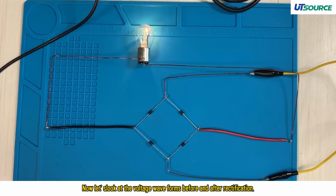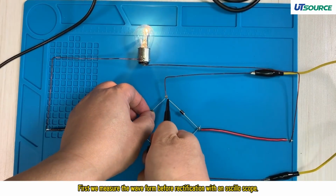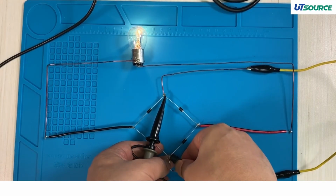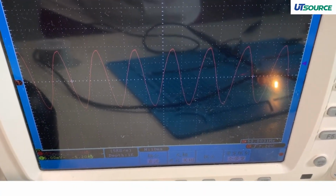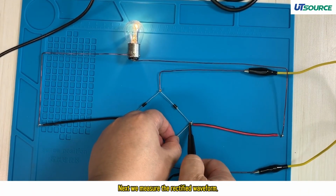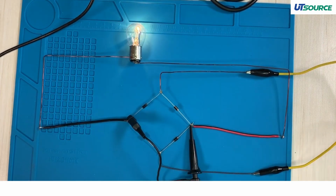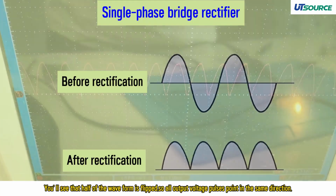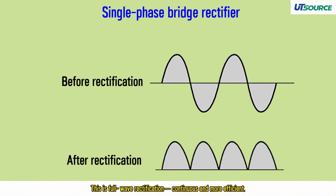Now let's look at the voltage waveforms before and after rectification. First, we measure the waveform before rectification with an oscilloscope. This is a sine wave AC signal. Next, we measure the rectified waveform. You will see that half of the waveform is flipped, so all output voltage pulses point in the same direction. This is full wave rectification, continuous and more efficient.